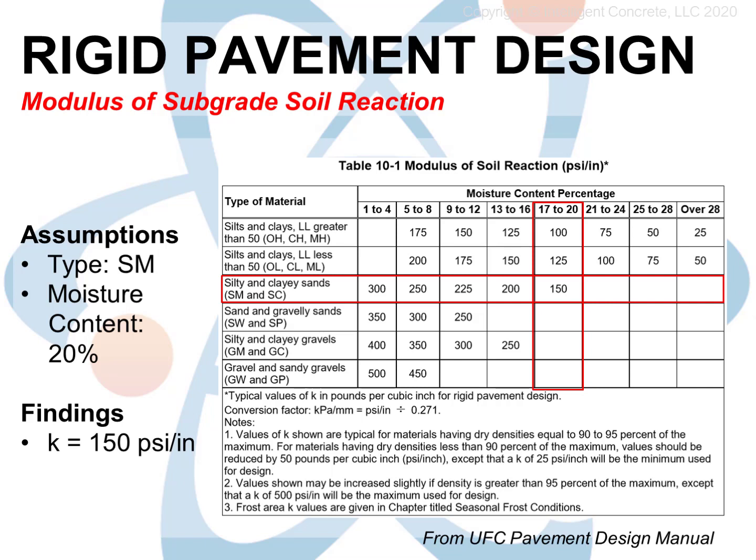The K of a native undisturbed soil can often be improved simply by scarifying, that is, digging it up a little bit, moisture conditioning, that is, adding a little water or allowing a soil to dry, and recompacting using proper machinery and techniques. For light-duty pavements, often this is considered adequate soil preparation prior to pavement placement.